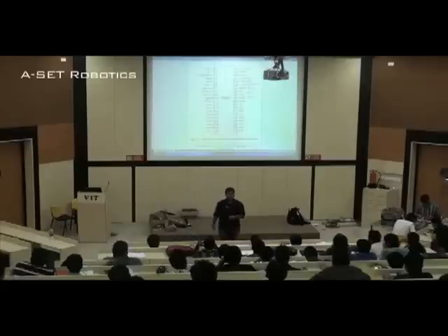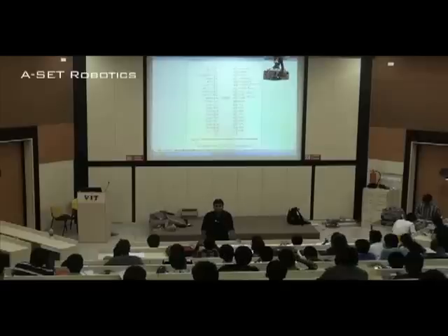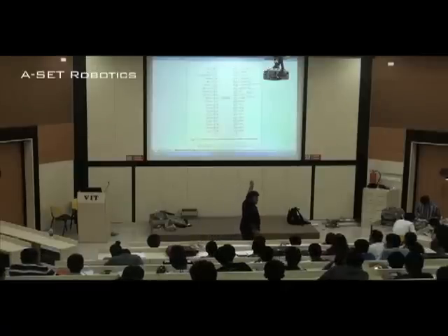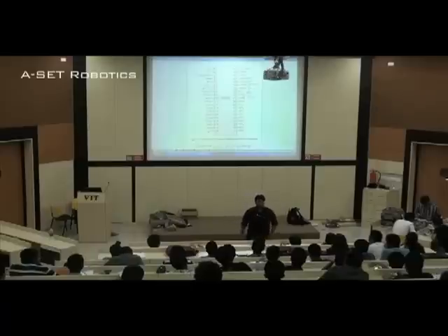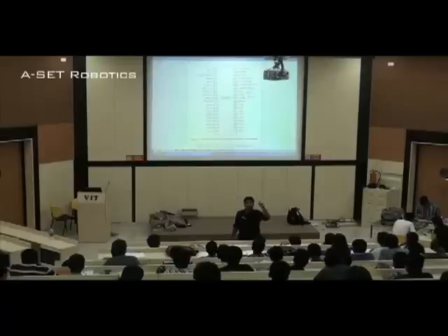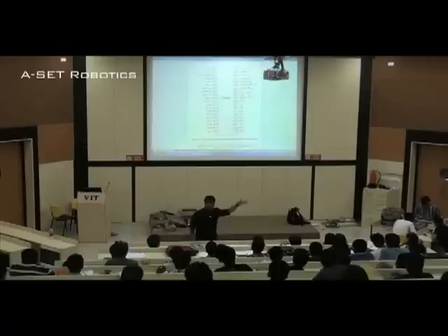Now IO/M, that is what is left. It indicates what exactly the microprocessor is doing at that point of time, whether it's doing an input-output function or a memory function. It is written as IO/M bar. If it is 1, then it's doing input output. If it is 0, then it's doing a memory operation.